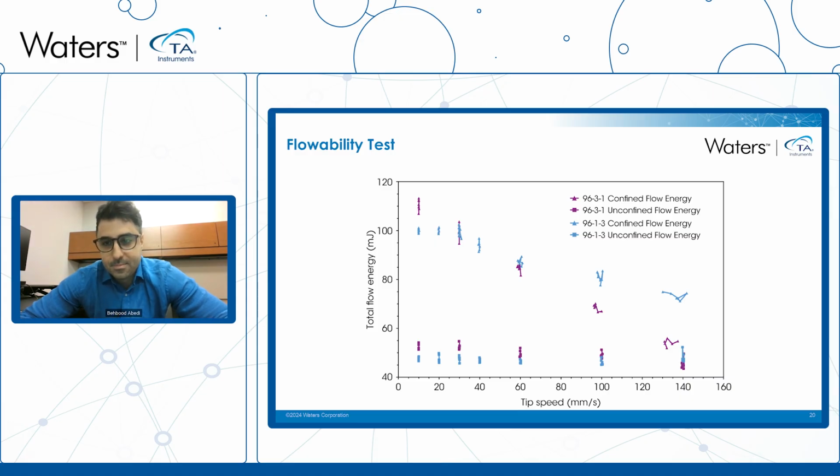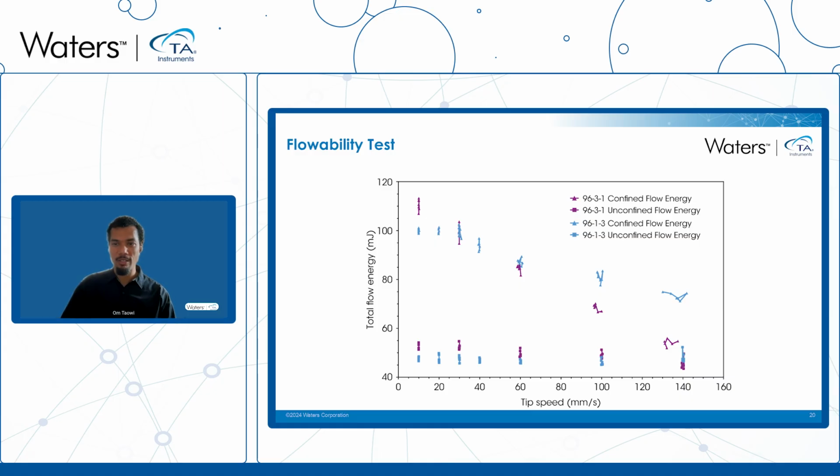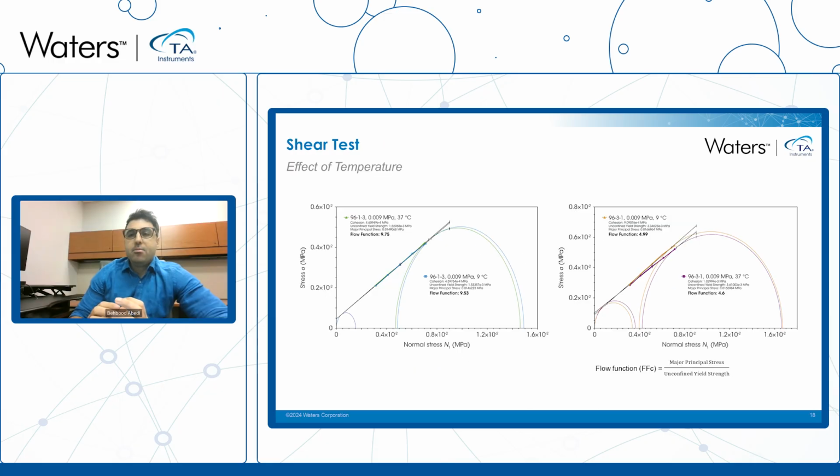Great questions and great answers. Our final question is, once I conducted a shear cell test, but the analysis did not show the first Mohr circle, what could be the reason for this? Yeah. When your powder is not cohesive, sometimes your cohesion value is very low. So the intercept at the y-axis may even go negative.